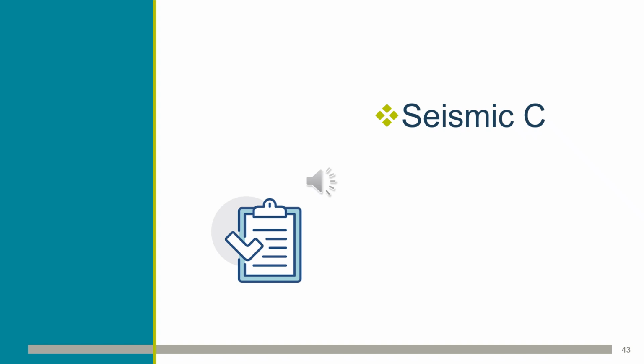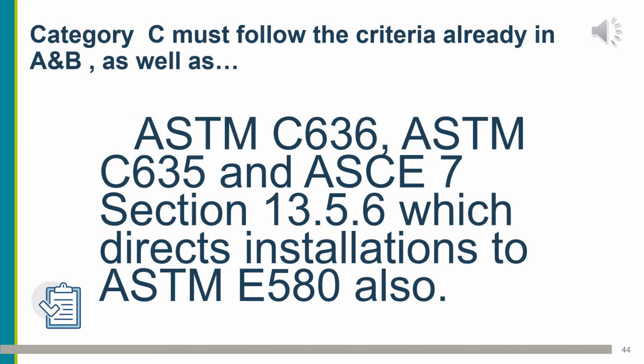And remember, everything that applied for A and B still applies here. ASTM C636, ASTM C635, and ASCE 7 section 13.5.6 direct you, for seismic C, to the installations of ASTM E580.